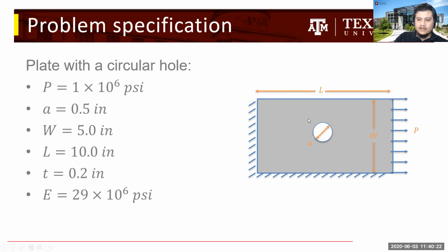But the addition of a circular hole in the middle of the plate is introducing a kind of nonlinearity in the geometry, because of which any available analytical formulation cannot be directly used here. Although there are certain analytical relations which are already present for a case of a hole in a plate, those solutions and results are for a case where the plate has infinite dimensions.